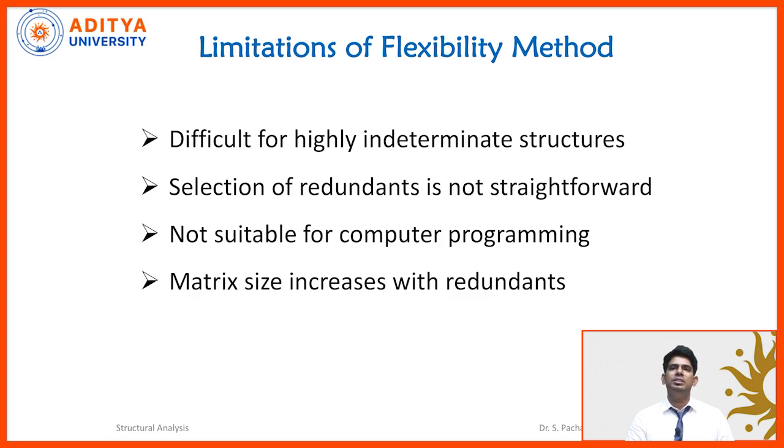Now coming to the disadvantages or limitations: difficult for highly indeterminate structures. So we cannot use the flexibility matrix for more complex structures, for example, analysis of a multi-story building like apartment buildings. Selection of redundants is not straightforward. That is also a major disadvantage. Not suitable for computer programming. That is a major disadvantage. Matrix size increases with redundants. When the matrix size keeps increasing, the complication of the problem also increases, and it becomes a tedious process.